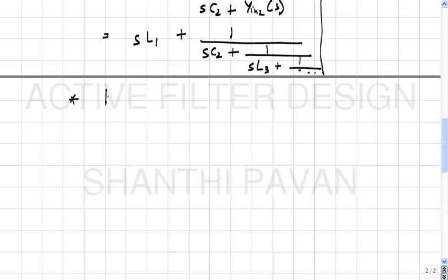Okay, so let's now, we also know that mod h of j omega square cannot be greater than 1/4, because the reflection coefficient magnitude cannot be smaller than 0, which means that if we are in a situation where the maximum power is being drawn from the source, that can only be v square by 4z0, and that is completely getting dissipated in the load, which means that the maximum voltage gain from input to output cannot exceed half, and that's not too big of a problem, simply because the peak magnitude can be scaled down to half.